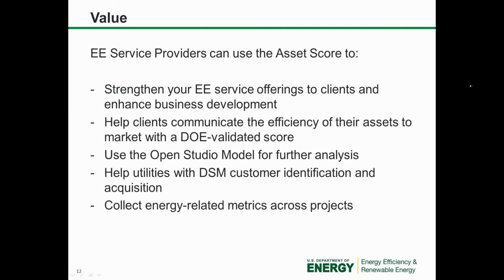One feature that we recently added, for those of you who are familiar with Energy Plus and Open Studio, in addition to the Asset Score report, you can now download the Energy Plus model or the Open Studio file and put that back into Open Studio and do calibration and do further analysis. For any of you that work with utilities, we have been in discussions with several utilities across the country because this is a tool that focuses on building systems and envelope. We feel like it lines up very well with the types of information that utilities are looking for to target and market DSM programs.